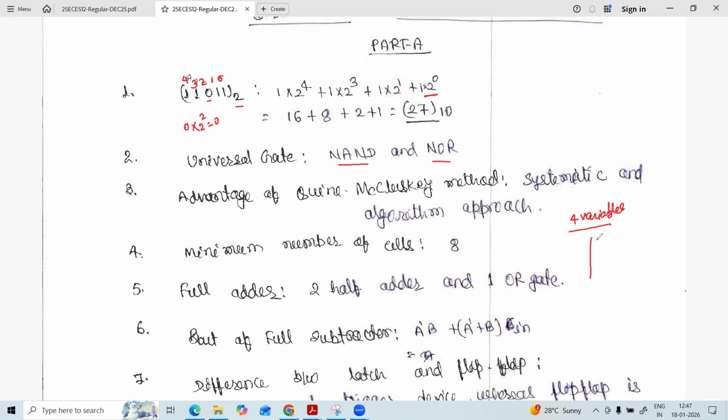When we have a combination of 8 adjacent boxes, row-wise you will not get anything common. Only column-wise you will get one literal as common. That's why we get the expression for this combination using a single literal. So we are able to eliminate three literals. So here the answer is 8.